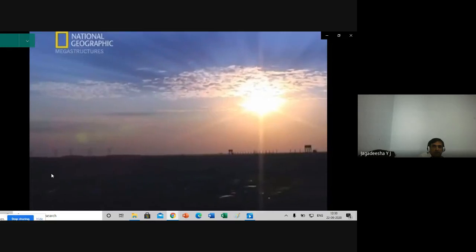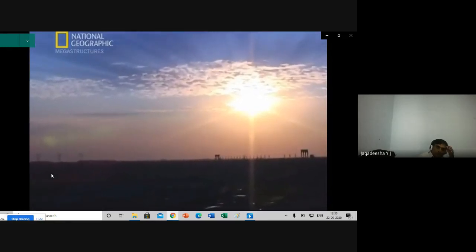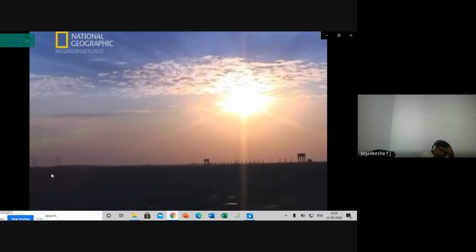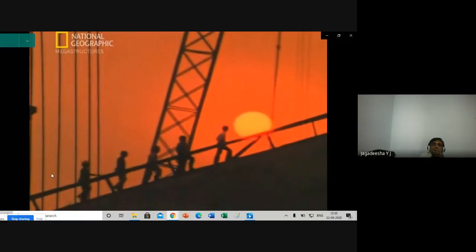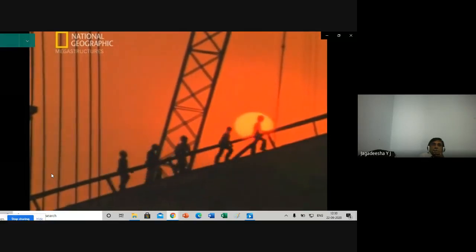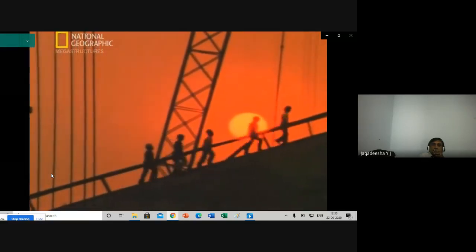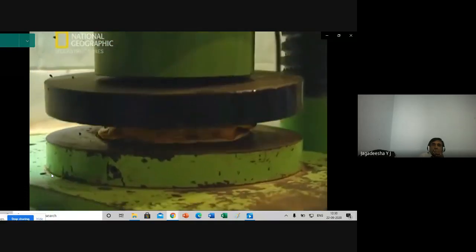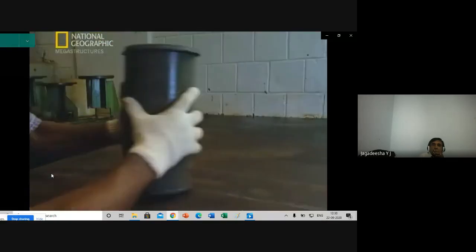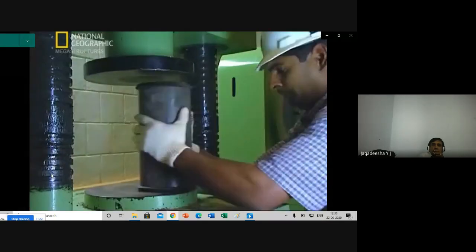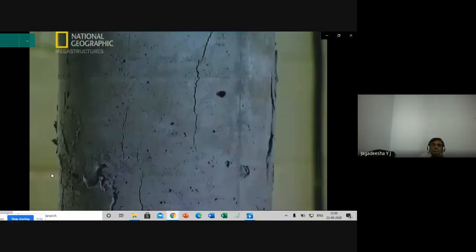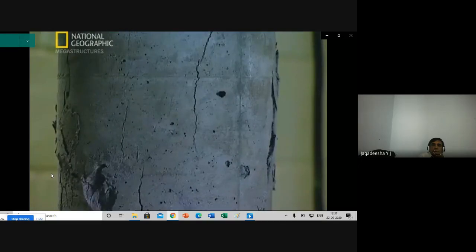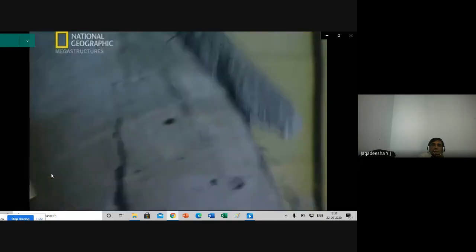And that wasn't the only problem. Temperatures in Brazil can easily soar past 40 degrees centigrade. If the huge blocks were allowed to set in the sun, they could reach more than 90 degrees. This too would cause weak spots and cracks. Engineers conducted test after test on concrete set in these conditions to see how it reacted to extreme pressure. Even good concrete has a breaking point. Concrete dried by the sun would be much weaker. A solution had to be found.